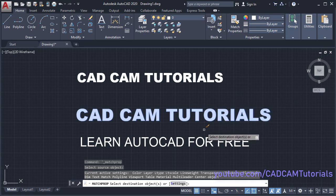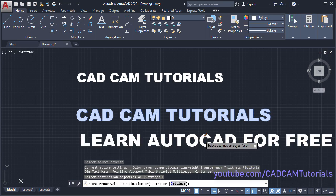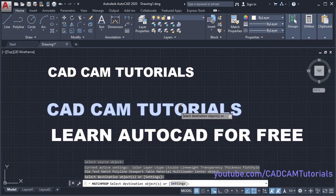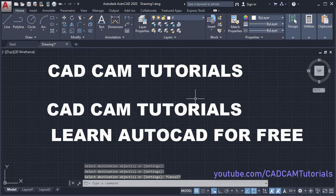So click on it. Then select destination objects. So you will have to click on the object to which you want to transfer properties. So I want to transfer properties to this text. So click on it, or you can also click on it. So hide get match. So in this way you can use match properties. Press escape to come out.